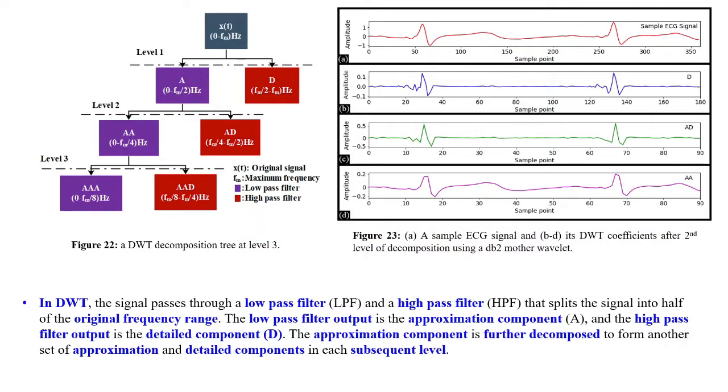So this is the difference between CWT and DWT. In the DWT, if you see the detail coefficients, they are not broken down again. But there might be some information hidden in these coefficients also, and we may want to increase the frequency resolution over here also. For that there is another transform called wavelet packet decomposition, where the approximate coefficients and the detailed coefficients are both broken down.